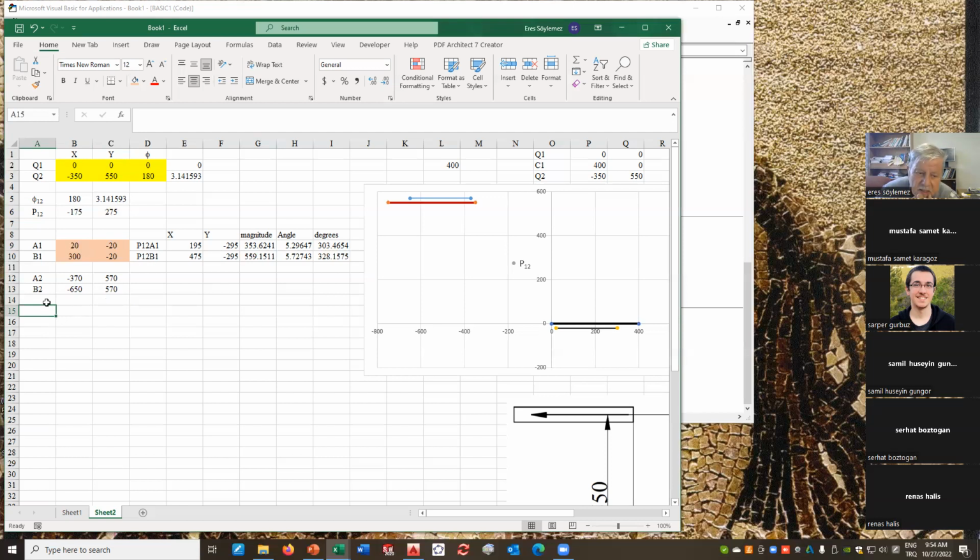Now for that, I will determine, if A and B are my moving pivots, the midpoint of A1, A2 and the angle A1, A2 makes, correct? Because the perpendicular bisector of A12 is going to pass through P12 and make an angle perpendicular to A1, A2.